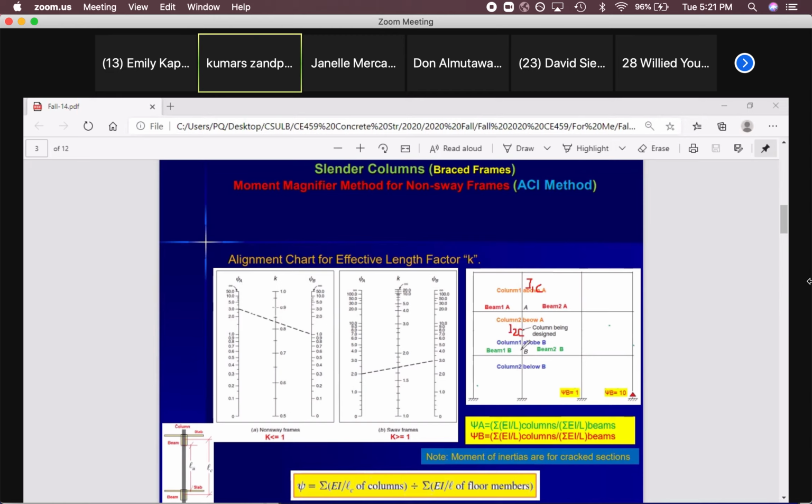Two, and each one times modulus of elasticity. So E times I1 divided by L1, meaning the length of this column. What's that length? LC. Yeah, LC means center to center. I put that here to refresh our memory. For this equation, use LC, center to center of the beams for the column. That's the length of the column.